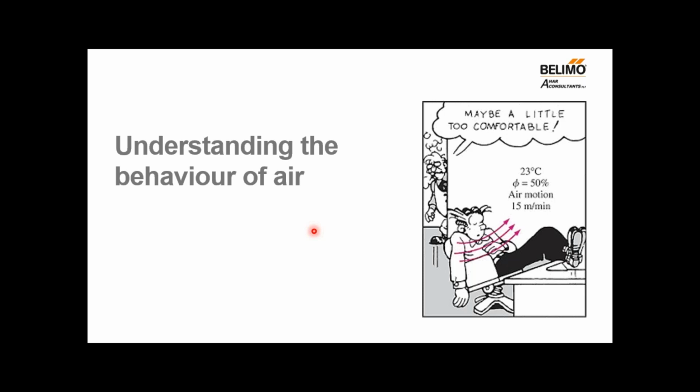Now, let us learn the behavior of air. So we know that temperature, air distribution, ventilation, and humidity play important functions in controlling infections. Although temperature and air distribution are well understood, I found that the understanding and care about moisture and gaseous contaminants in building are still lacking. With the COVID pandemic, we need to put more effort into controlling the humidity more closely.